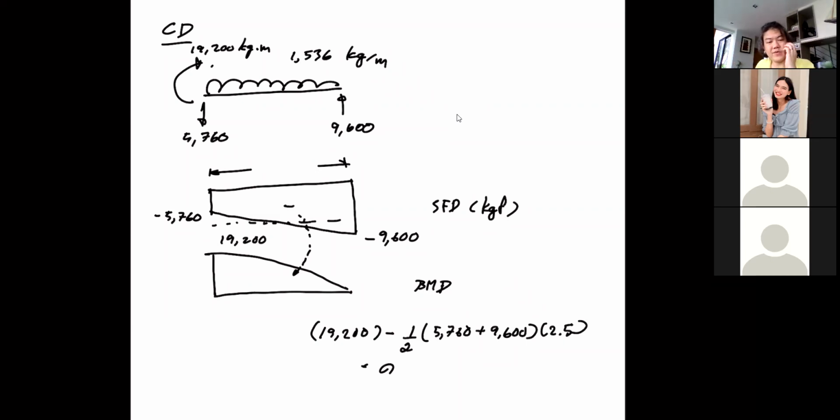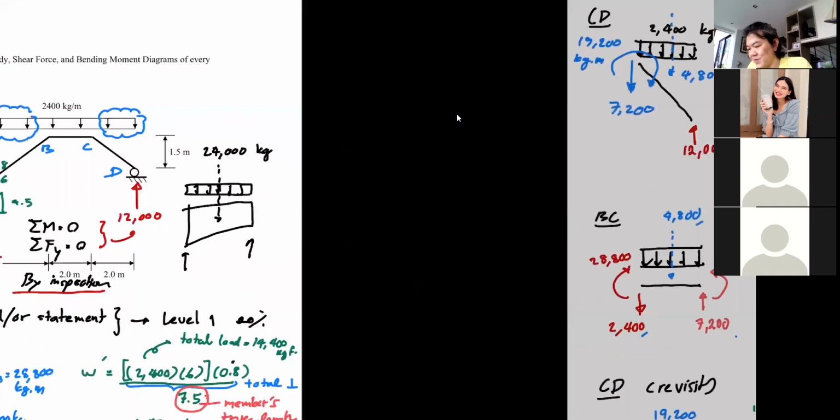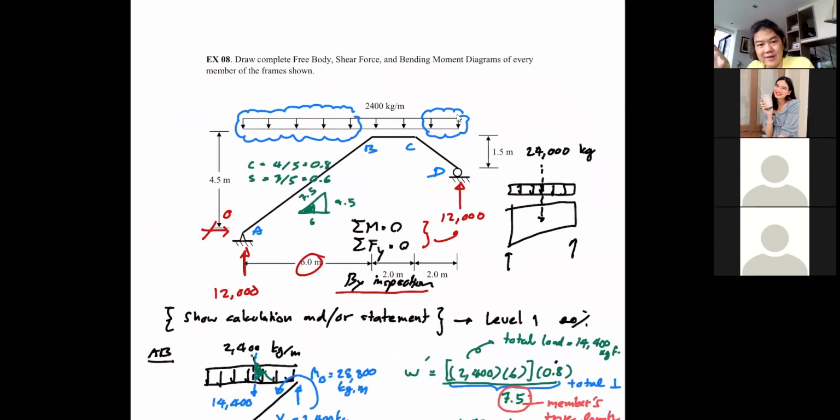Okay, so you see, because of the nature of the structure, we have the frame and we push everything down. So chances are everything is going to bend like a typical simple beam. So you have the positive moment throughout the system.